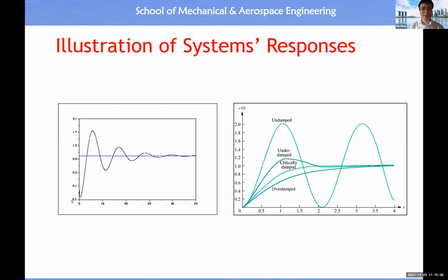For example, here this is a previous steady state, and this one is a new steady state. Then the actual output will take time, and have this kind of behavior before it converges to the new steady state. For this example, the initial steady state is at this point, then the new steady state should be here. Then you see the actual output will take time before it reaches the new steady state. So this slide helps you to understand the relationship between steady state and the transient response.